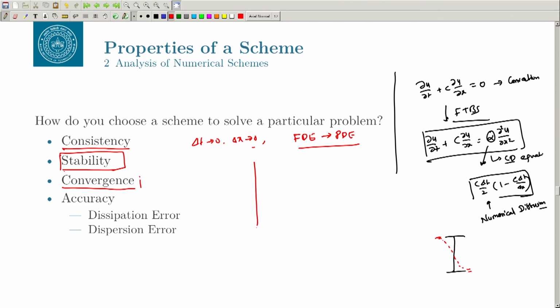Typically, you might be looking at the curves, for example, your continuity, x momentum, y momentum, and you would be looking at a number, let us say 10 to the power minus 5. You started from a value, let us say 10 to the power 0, and then you went all the way to 10 to the power minus 5. Then you say, okay, this is the acceptable level. Let us say your equation is N(u) = 0, and your numerical solution is N(u_n) = 0.